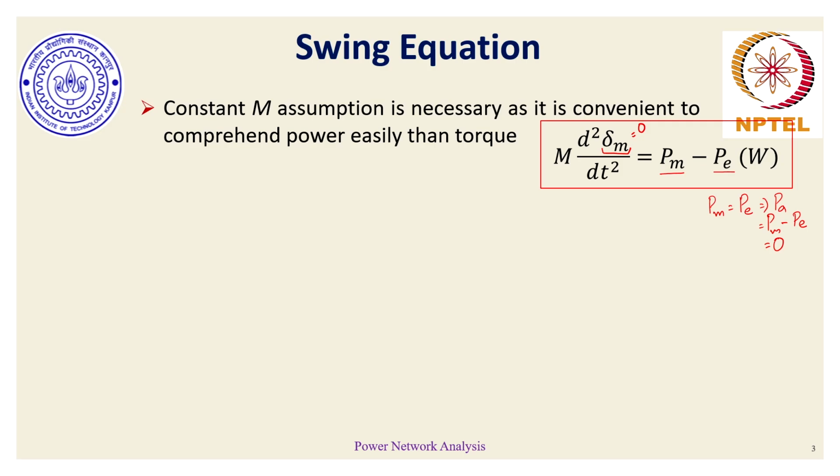Hence the rotor rotates at synchronous speed with respect to the stationary axis on the stator. Alternatively, the rotor speed and the rotating stator MMF in the air gap have zero relative velocity, because both rotate at the same synchronous speed, as dictated by the operating frequency f and the number of poles in the synchronous machine.